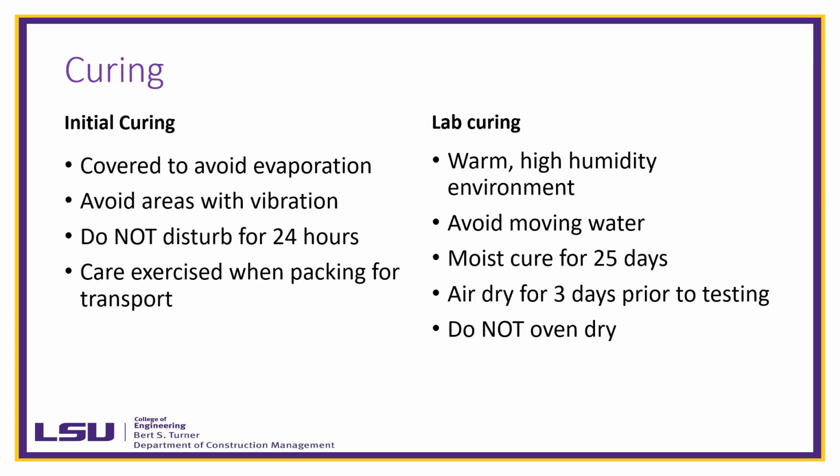So curing: initial curing is very similar to typical standard conventional concrete. Cover it, avoid areas with vibration, and don't disturb them. Make sure you pack them nicely and take care when you transport them back to the lab or wherever they are. Lab curing is going to be very similar.